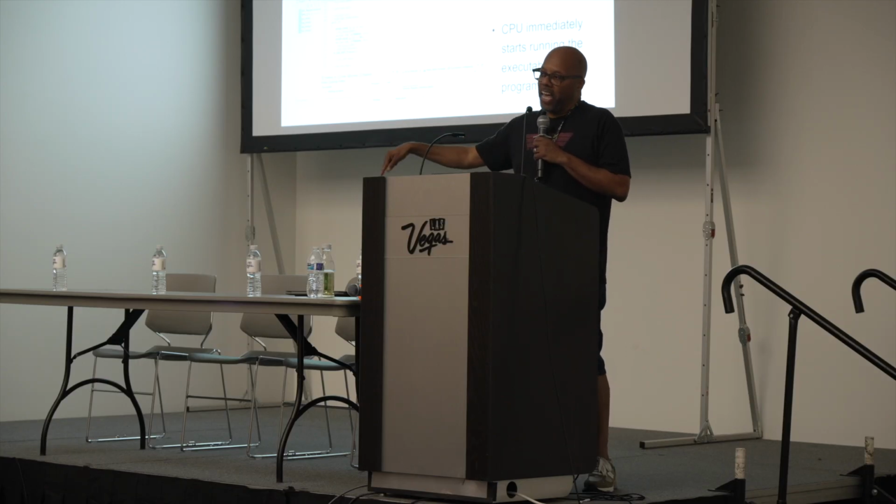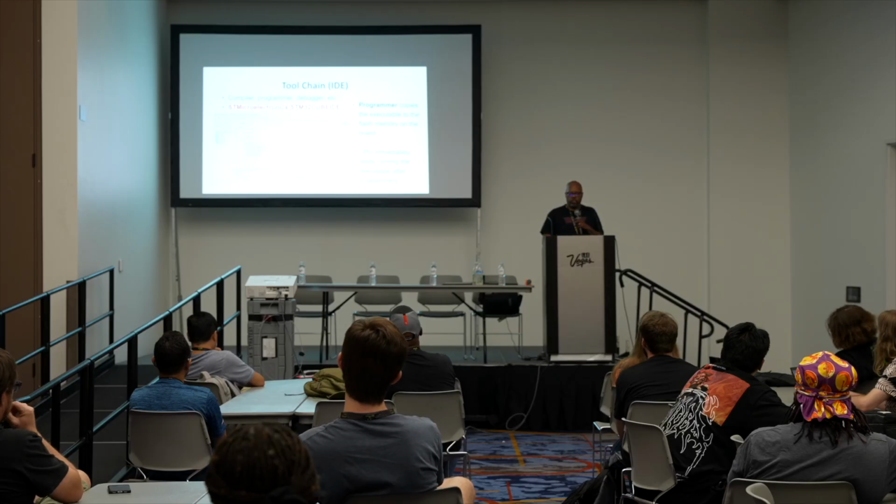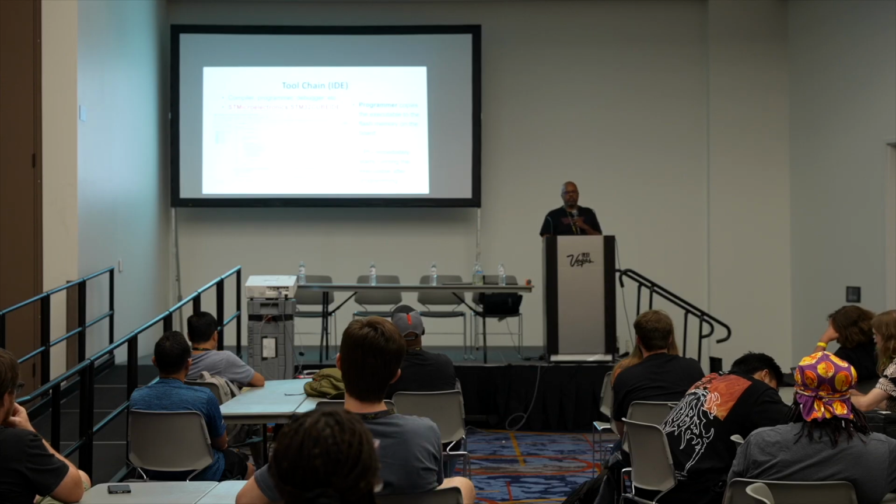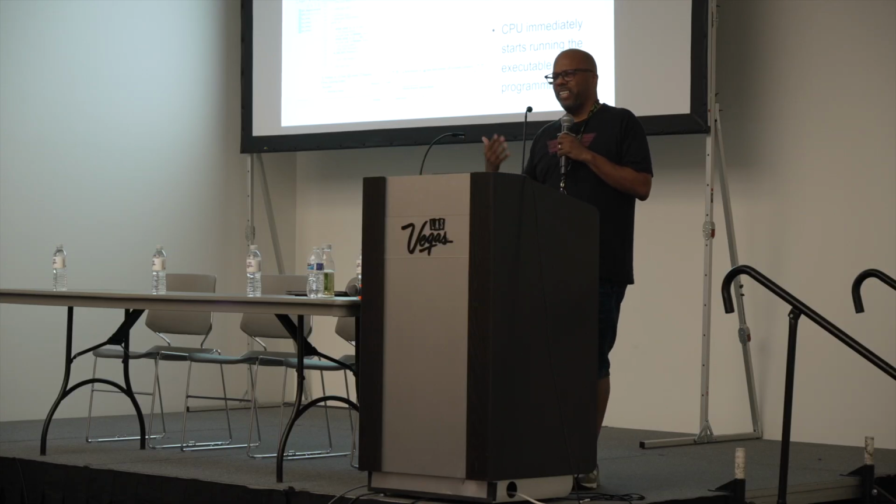So this thing uses a cross-compiler, and the last step is to take the cross-compiled executable and program it into the flash of the actual device. And that's what a programmer does. So it's some programmer software. Usually this thing has an extra button in there. It's like program, and it just programs it onto the embedded device after you've compiled. Okay, so IDEs, though, don't look that much different.